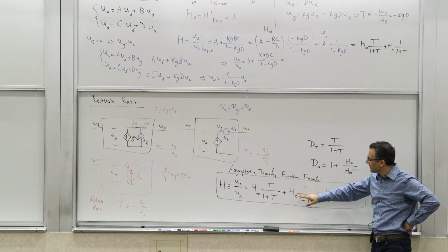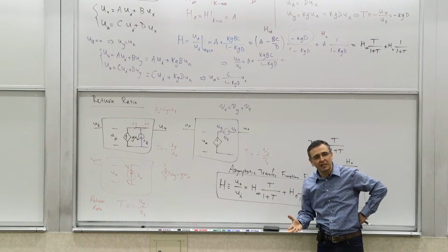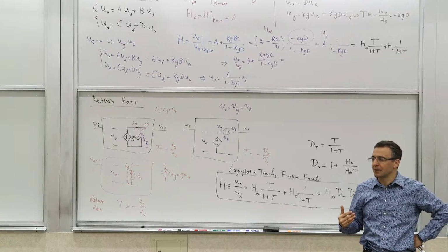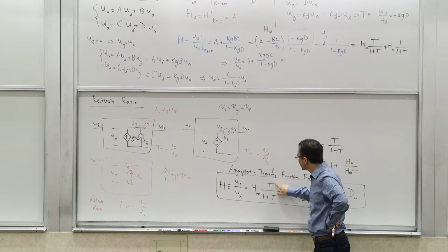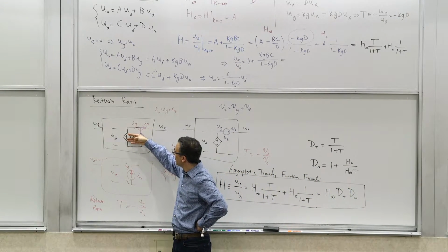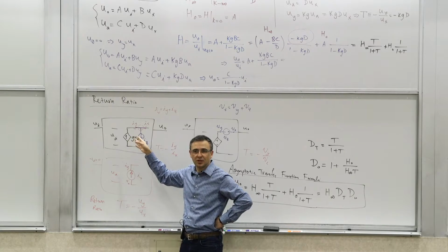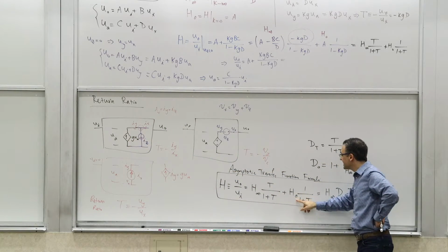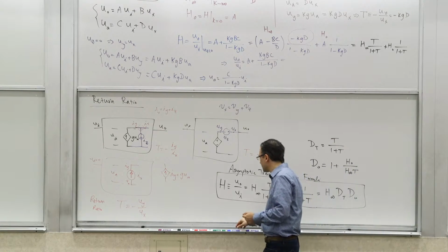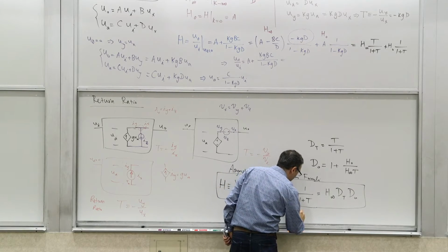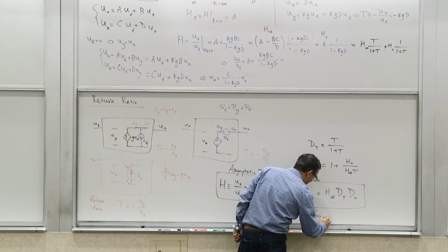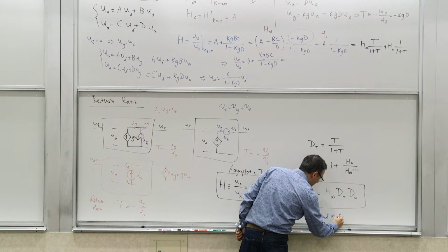Now, what is this term? So we know what this is. This is really h infinity, what the loop does with maximum feedback, with a lot of feedback. The return ratio, we know it's a measure of how much of the signal that this dependent source generates comes back to itself. It's a measure of the feedback. What is this h0 a measure of? It's called direct transfer function, direct forward transfer.